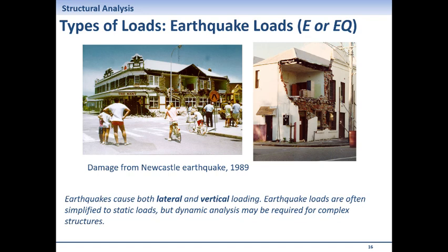But if you are dealing with a complex structure, like the one that I just mentioned, a nuclear reactor building, or a high-rise building, that approximation becomes too rough for that type of structure. Then you must do dynamic analysis. If you look at the earthquake standard in Australia, 1170.4, it gives you different avenues, different methods to estimate and apply earthquake loading on a structure to design.